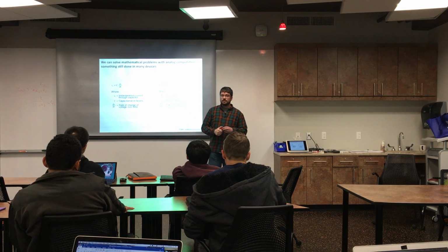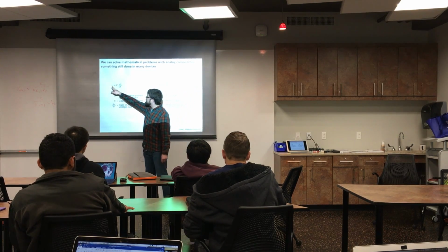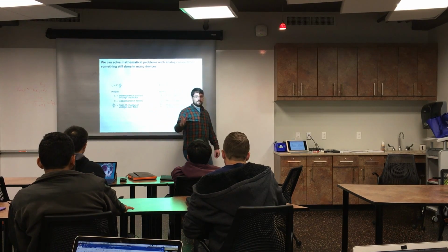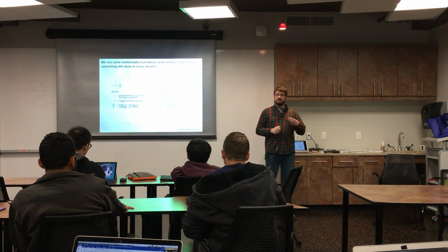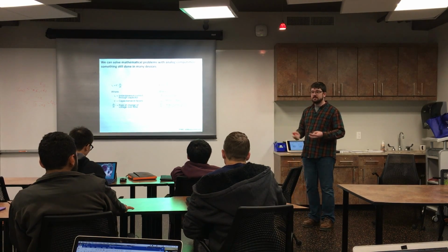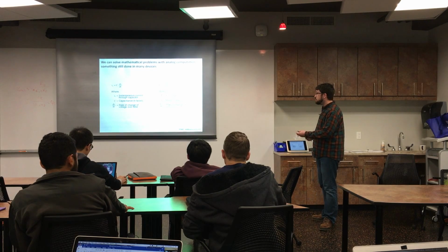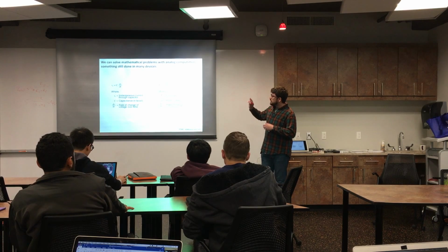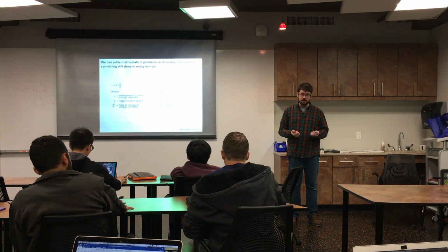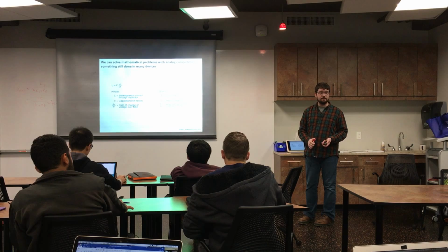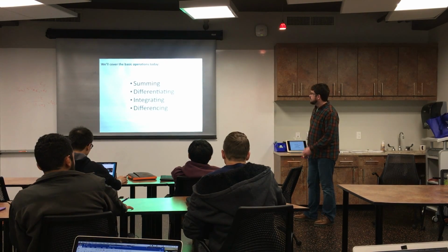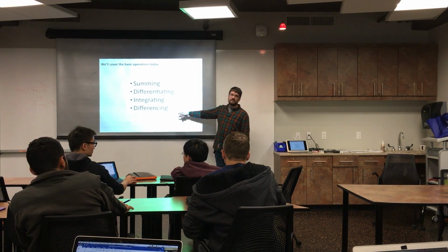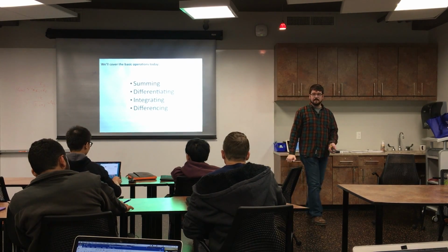Now let's look at an electronic circuit where we have the current through a capacitor equals the capacitance of the capacitor times the change in voltage with time. So we can start seeing a parallel between solving equations of physical systems and equations of these electronic circuits, right? So we can use the basic components like capacitors, resistors, and in this case operational amplifiers to solve equations like F equals ma if we wanted to. And that's the only way we had for a long time to do so. So we're going to show you summing, differentiating, integrating, and differencing with operational amplifiers at a pretty high level.